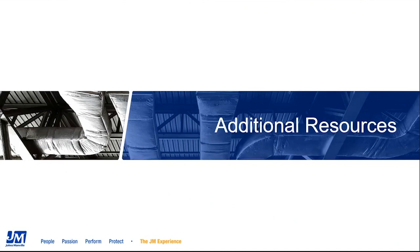The in-package R, or the installed R, is once you compress that product to 25% of the insulation thickness, that gives you the installed R value. So two very different pieces there. Really, you want to reference the installed R value when you're looking at duct wrap. Excellent.